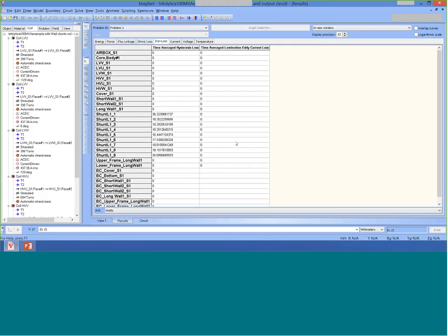And there we have, again, the core. In this case, I didn't have a loss curve for that particular material, so we don't have a hysteresis value, core loss value, but we have the core loss values for the shunts, which again were totally modeled. They weren't modeled with the surface impedance.